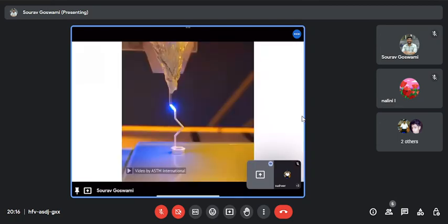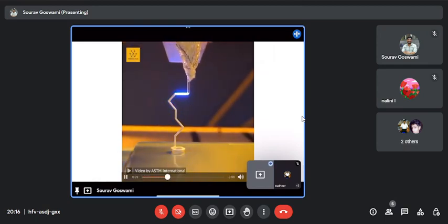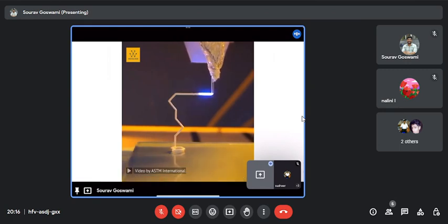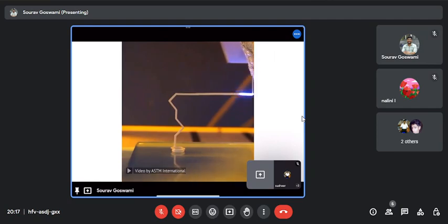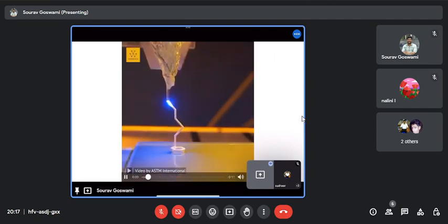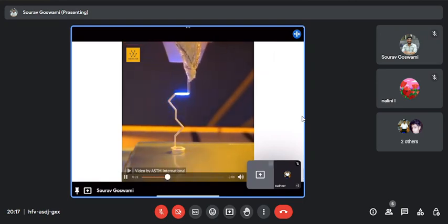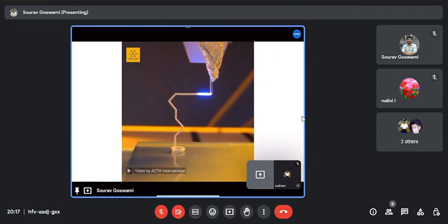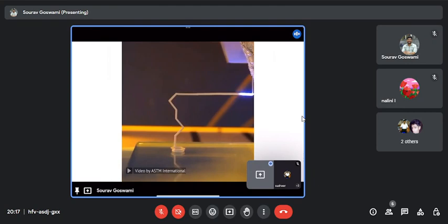And in the next slide, we have an example of direct writing. So as we said, if the deposition head or the energy source is flexible and can freely move around, there need not be a fixed build direction. So as we see in this case, it appears that the printing is occurring in free space without any support structures. I'll just play it again. So as you see, there are no support structures. There is no fixed build direction. And yet the structure, which is actually a combination of polymer and ceramic, is standing.